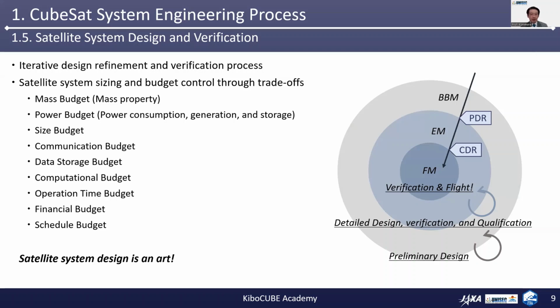This process through the BBM, EM, and FM is illustrated in this figure as an arrow. The design accuracy gets improved in each design process. So it is very important that the flight model design is clearly defined in the previous EM process, and you don't need to change the design of the FM from that point forward, especially in terms of the verification aspects.